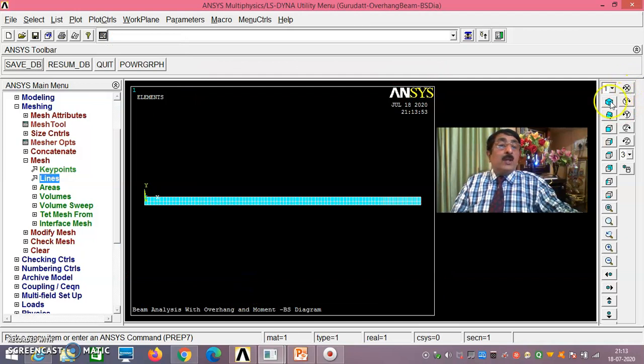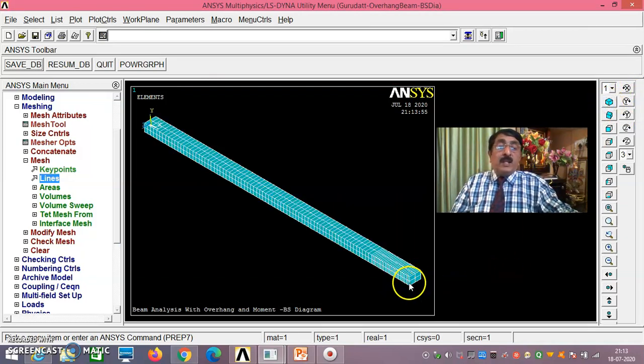Now if you go for isometric, you see here the beam is oriented wrong. This depth is 0.2, this is 0.3. 0.3 should be parallel to the y-axis. The depth should have been more, but now it is the width. In this way, if you load on this, naturally you get a pseudo deflection. The deflection will be more, and the moment of inertia you get will be less. As a result, unnecessarily the bending stress you get will also be more. This orientation is wrong. Can you understand?